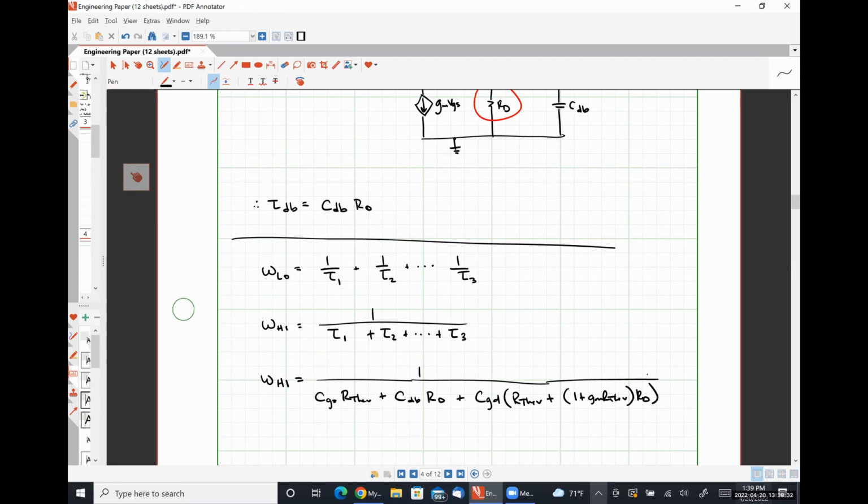That would be the hardest type of thing that I could ask you: let's add that little output network like you had on your design project and see how that influences the frequency response. It's just another transfer function to include that is literally a simple voltage divider circuit that will give you, I think, one more zero and definitely one more pole. So, all right, that's enough out of me.